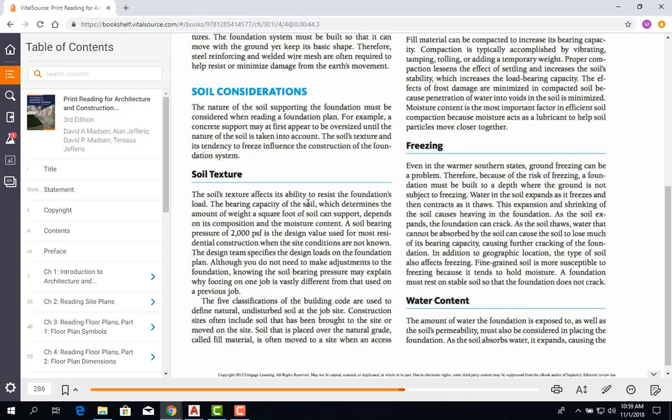Remember, all that weight is coming down from your structure, all the way from the roof, transferring down to the support members, going to your foundation. The foundation is being supported by the soil. So you need to know what type of soil do I have? Can it sustain my building? Now of course, the higher you go, the deeper you want to do your foundation because it's holding. So let me show you some images here that talk a little more on this.